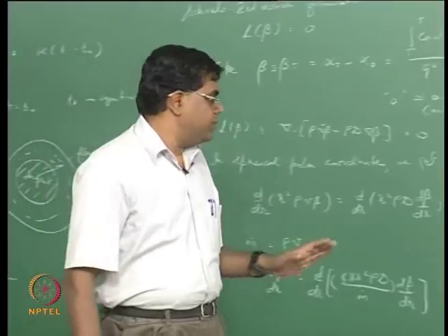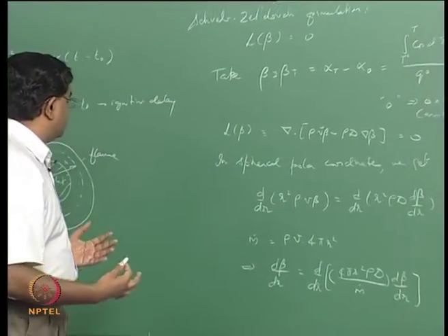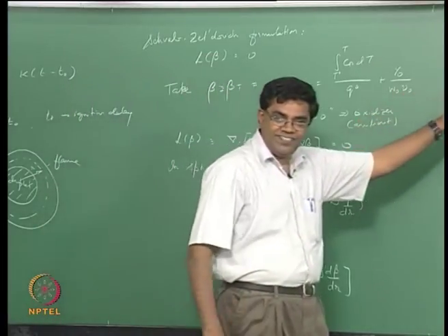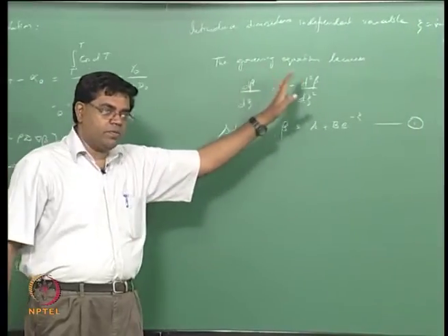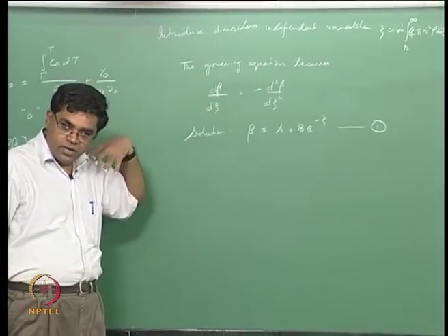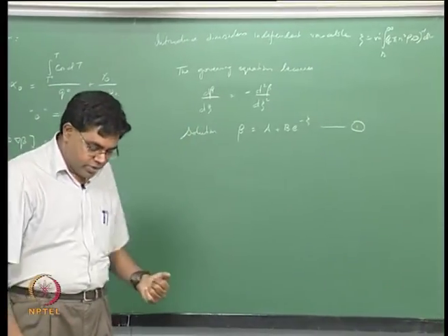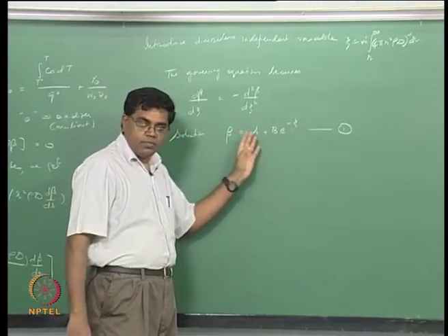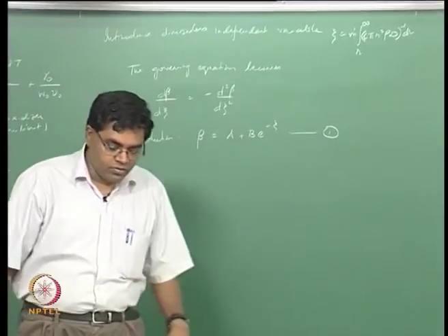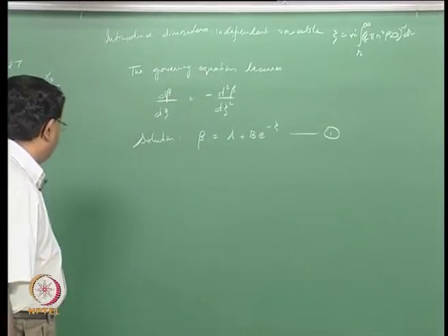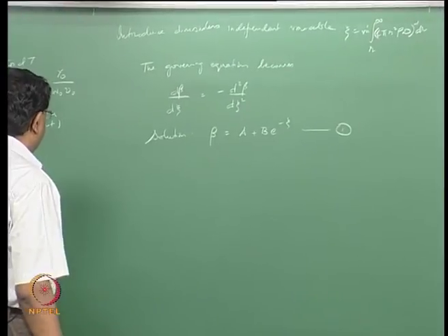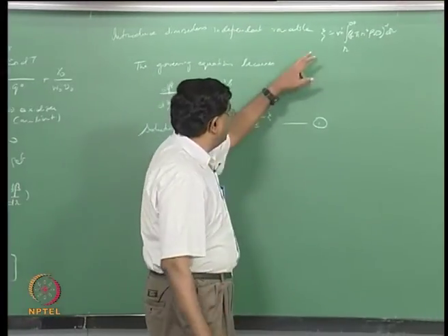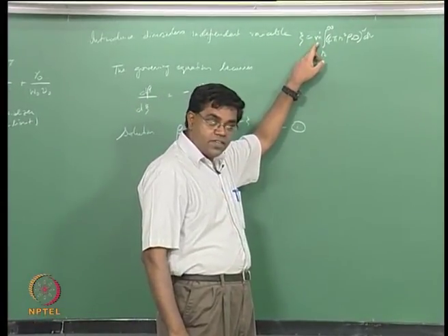Alright, so strictly speaking I have not really said from here on, when the mathematics started, that I am working on the droplet problem. The droplet problem is going to show up only when we start applying the boundary conditions, which are needed to evaluate the constants of integration a and b, which come up because we have just solved a second order equation. So we have two boundary conditions that need to be provided, and keep in mind we don't quite know psi as well. It involves m dot, that is the unknown.